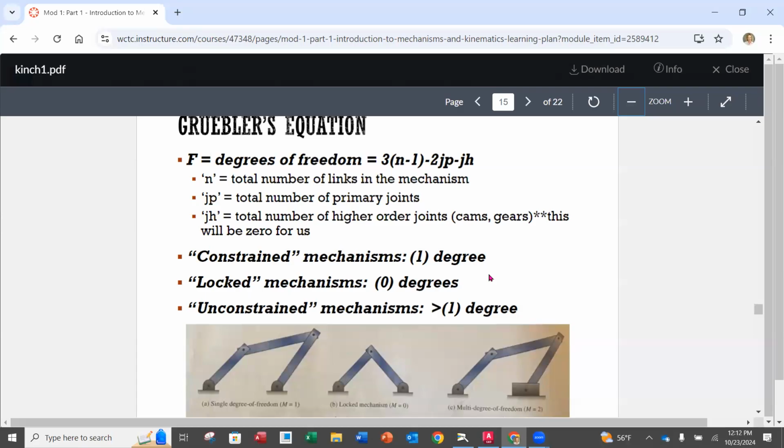We had looked at the vice grips the other day. We held it on one handle and then we let the rest of it dangle down below. But while keeping the one handle in place, I really just had to move the other handle, 1 degree of freedom, in order to get that jaw to open and close on the front end. Okay. So when there's 1 degree of freedom, first of all, it's very easy to use. There's only one thing to do to get it to do what it's supposed to do. It's not complicated. So it's desirable to have 1 degree of freedom.